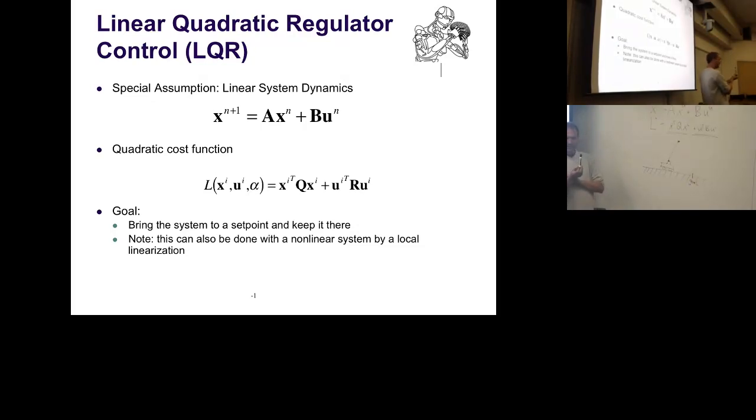So let's do it the dumb way. Let's assume I'm here, I want to keep this upright, and I want to go over there. So I just create a PD controller to put me into that state. Okay, I could do that. Unfortunately, this is not going to work. Since when I start accelerating towards the goal, the pole will tilt backwards due to its inertial properties, and I will fall over, annoyingly. So what I actually have to do, interestingly, is first go backward, have the thing tilt forward, then I can move there, then catch the pole and balance.